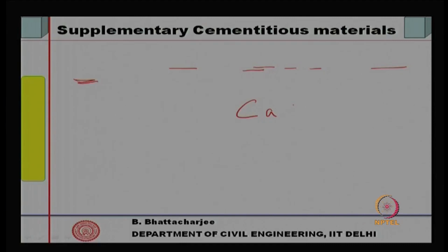Lime surki construction has been pretty well known. Similarly, volcanic ash with lime can also react and produce cementing material. Now, these materials are nothing but lime, which is calcium hydroxide, plus silica or alumina in presence of water. So, you see, the same ingredients as cement.